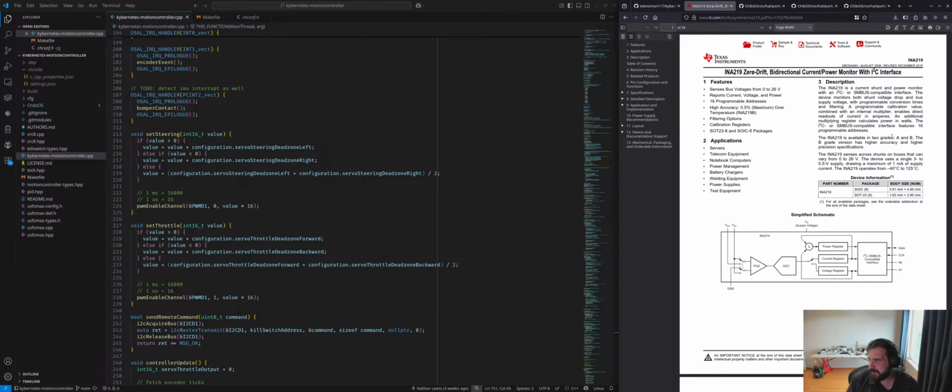So what that means is that the way you measure current draw in one of these systems is you use what's called a shunt resistor, and typically these are extremely low resistance. They're very precise, but they're very low resistance. So in the case of this one, I'm using an 8 milliohm resistor, and if you apply Ohm's law here, V equals IR.